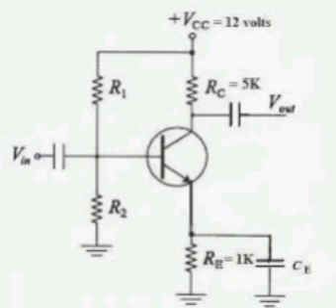You can understand this by drawing two tetragonal end-centered unit cells side by side. If you join all four end-centered lattice points to common lattice points of the unit cells, the new unit cells formed will again have a single four-fold axis of symmetry, and as you can observe, it is primitive tetragonal again. Hence, due to symmetry, there is no end-centered unit cell. Out of 28 possible lattices or unit cells, there are 14 which are not mentioned in the Bravais lattice because of the same reason, symmetry.